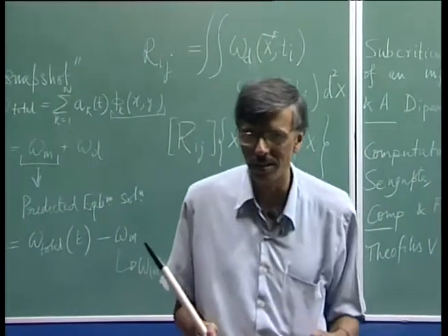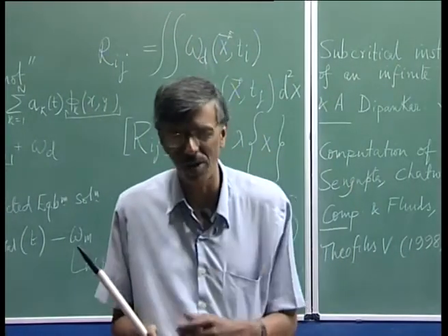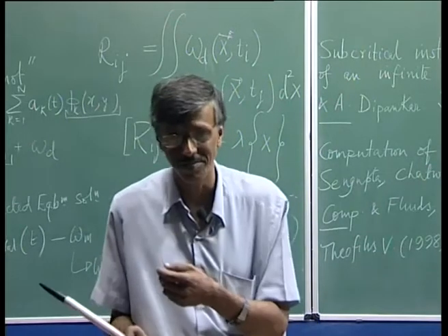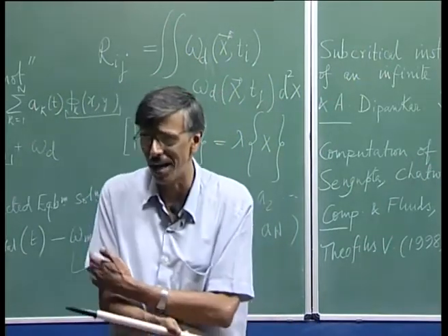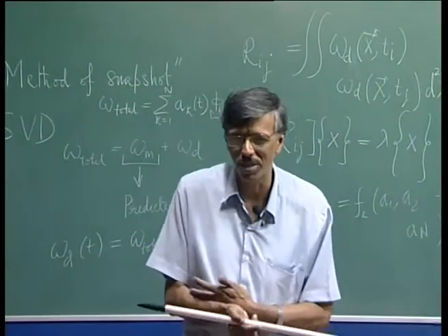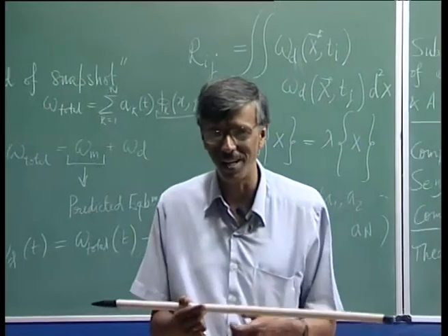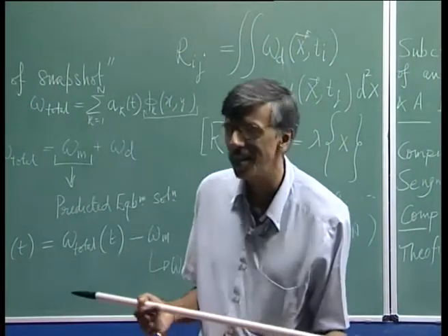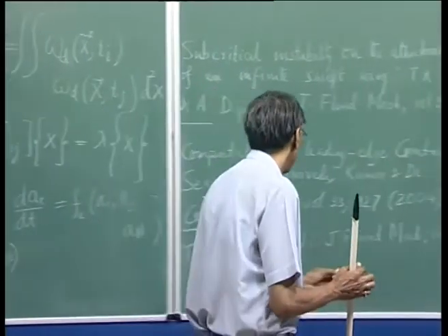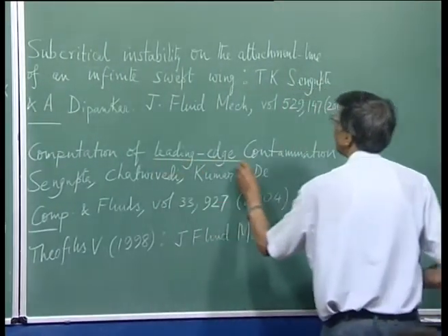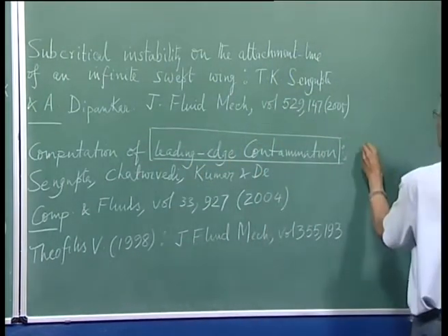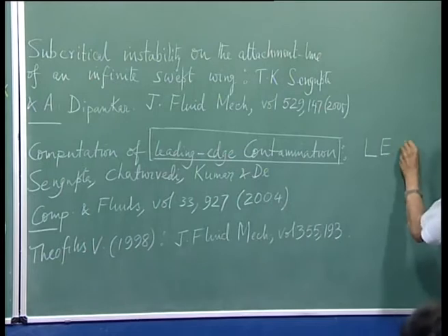When you calculate the drag estimate for the wing, you assume the flow to be turbulent right from the leading edge for that reason. Because in actual wing design, if you do not take care, the flow actually becomes turbulent right from the leading edge. And this problem is what is called leading edge contamination, or we will call it LEC.